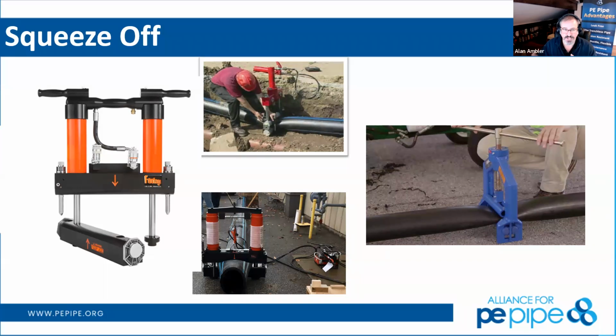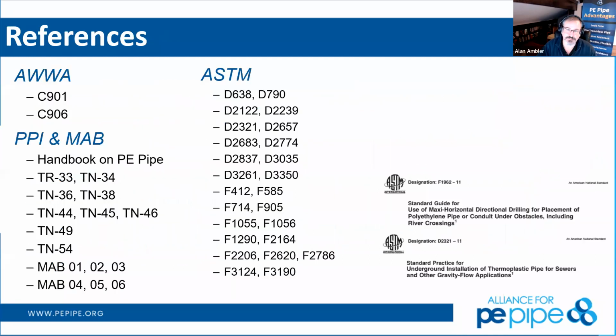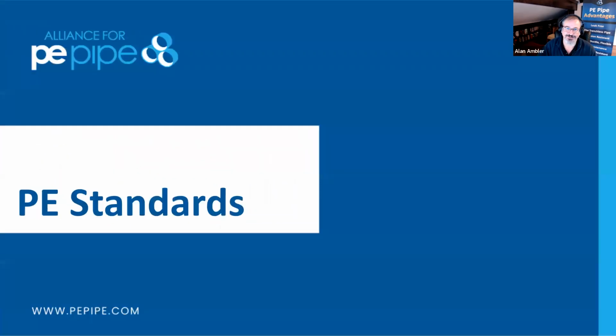And again, we're not deforming or hurting the pipe beyond its allowable yield once we follow the ASTM standards that control that, and that pipe section is going to live the rest of its life as designed. So it's definitely a robust pipe material product that will let you do that. We're not going to be able to squeeze off any other pipe materials in that manner.